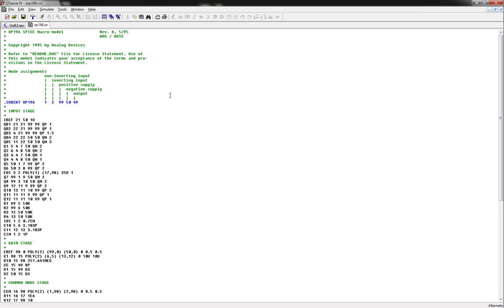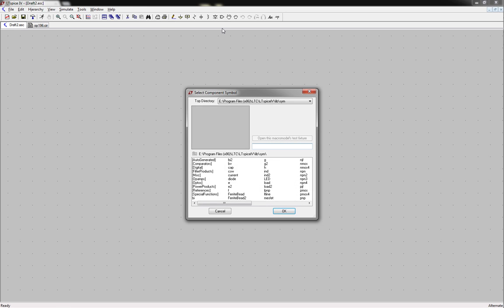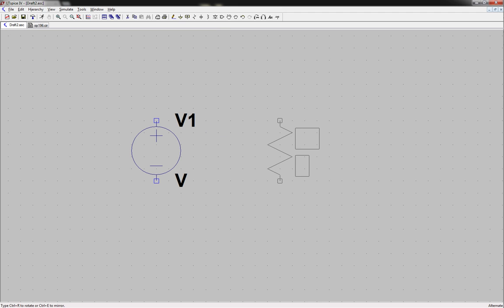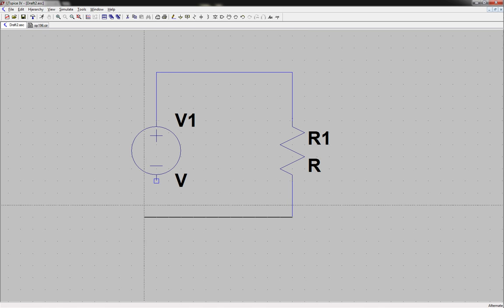So let's say a simple circuit like a voltage source and a resistor, and you were just going to connect those up like this. I'm doing a horrible job of it. You're just wanting to connect them, and that's what you want to do. I did that really fast here, but you would actually have to label V1, and then that's connected to node, let's say we label this 1. R1, pin 1 would be connected to node 1. R1, pin 2 would be connected to node 2. Node 2 would be connected to ground, as well as the minus of V1 is connected to node 2.